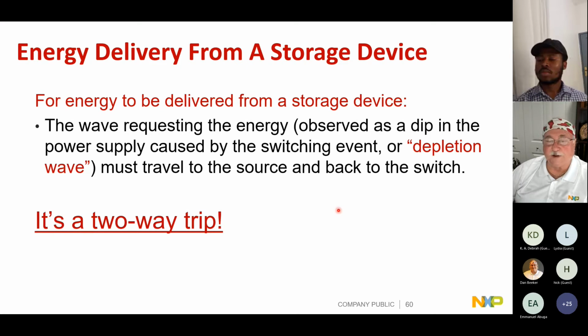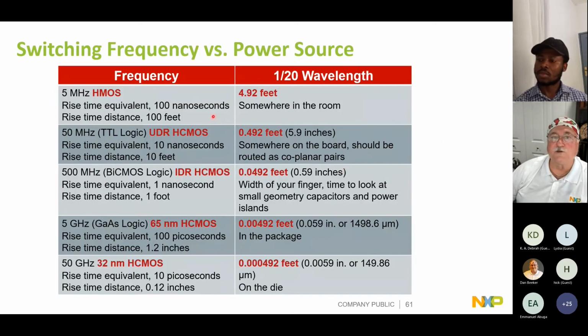So it moves in that transmission line until it comes to a discontinuity, a change in impedance. That's where reflections occur. When the geometry changes, then there will be a reflection depending on whether it's higher or lower impedance. It tells you whether you source energy or you lose energy. And that's why it's so important to know this. So this is the chart that I made for power supplies.